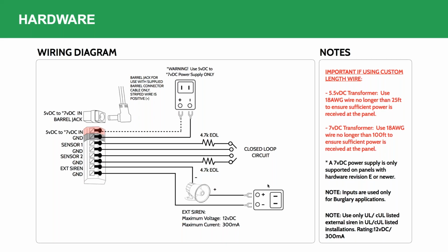With the 7-volt transformer, that's allowed us to go up to 100 feet with 18 gauge wire. We know if you do the math, you can get closer to about 190, and you're going to get more like 90, 95 feet with 22 gauge wire. That's helped us over the last year and a half curb any of those voltage drop issues that we did run into in the past.